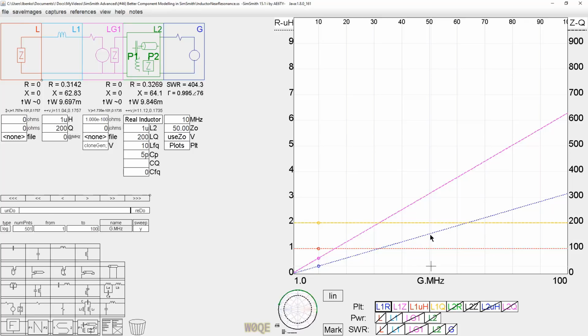And while we talked about the fact that the resistance is rising faster than it probably should, it's hard to say for sure how fast resistance rises. The resistance term here is lumped between the actual resistance or the actual impedance of the wiring and stuff in the circuit to get from the pad on the part into the circuit, etc. But it also includes the loss in a core material if it was an inductor. It also includes the dielectric loss in a capacitor. But it generally is not that great, and so this is too aggressive of a rise.